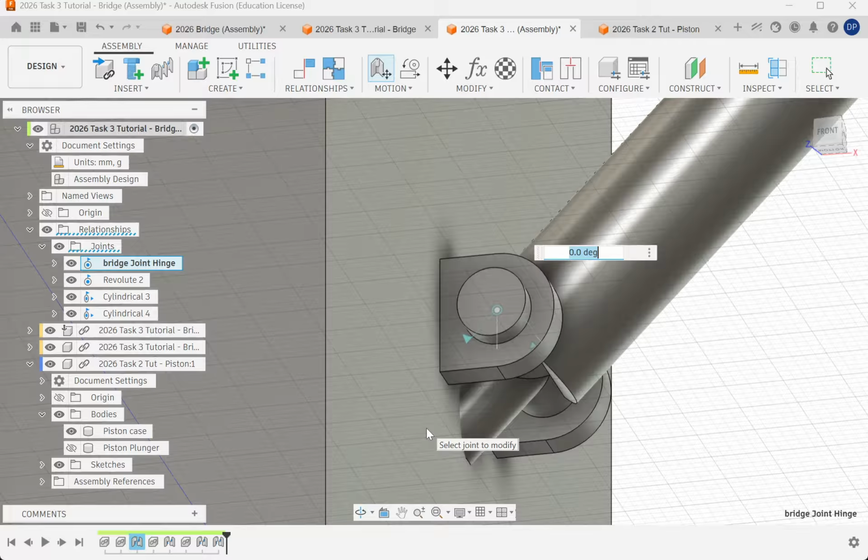Yes? Make the needle shorter. Yes, you can cut the needle down. I wouldn't though, because you've got the tubing on it. But by the same extent, if you want to make the needle shorter, what can you make longer? So over here, the supports, exactly. This support, we made it close here. You can just make the support longer as well, so it's offset by more distance. So that's why we bothered modeling the needle in there.